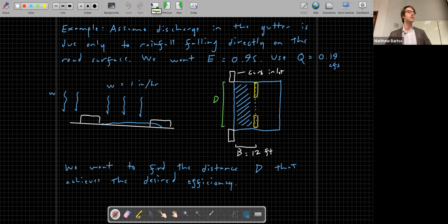So where is that discharge coming from? The roadway. So the discharge is coming from the rain that's falling on this area, right? Is there any other component of that discharge? From the gutter and the bypass discharge. Right. So the discharge along the gutter is the sum of the bypass discharge from the inlet upstream added to the amount of discharge that's being created by the rainfall falling just upstream of our curb inlet.